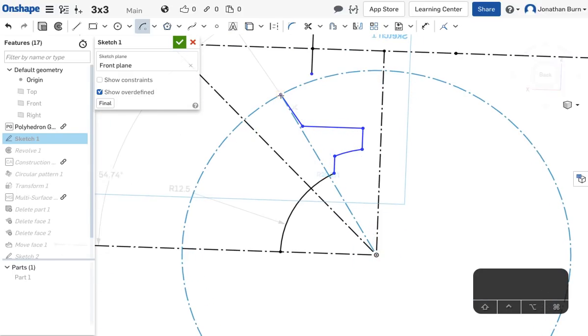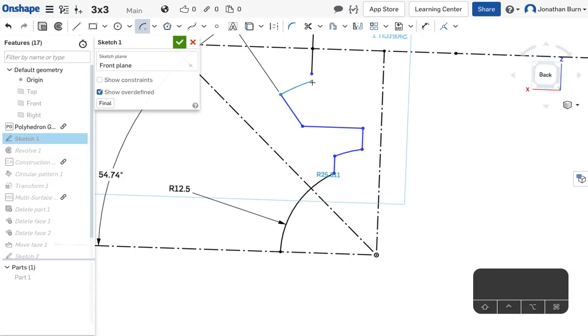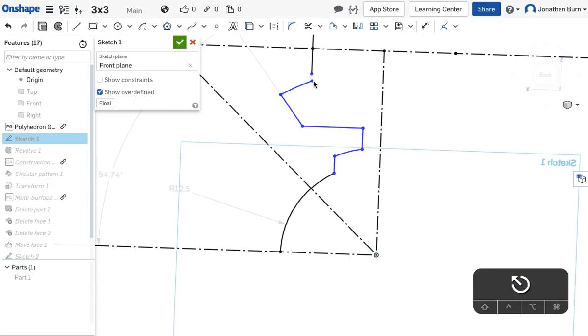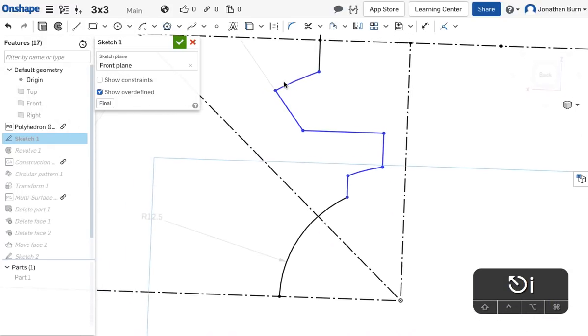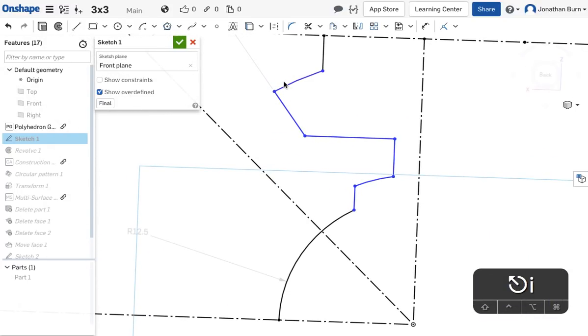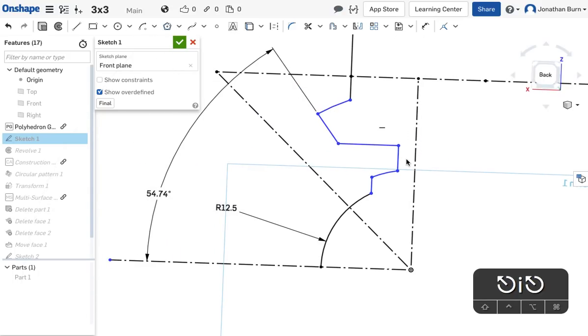Click on the center, click on that point, and click down over here, press escape, and then you click on these 2 points and you press I, and that'll join them together. What that will do is make it actually a spherical cut instead of a cylindrical cut. So I'm going to press escape. Just click the check mark.